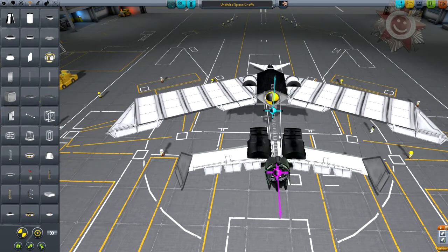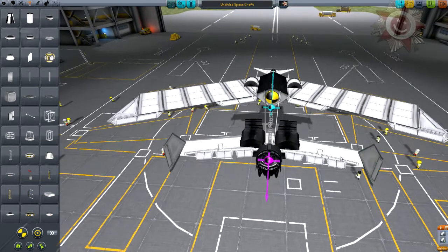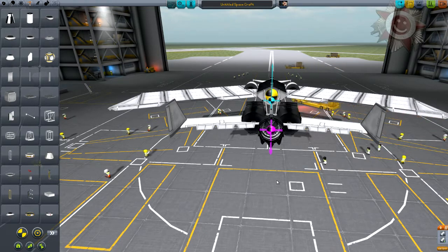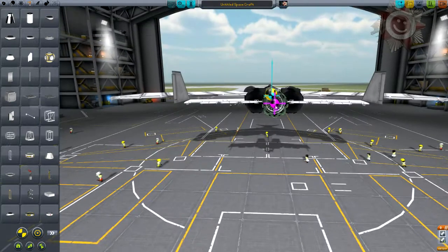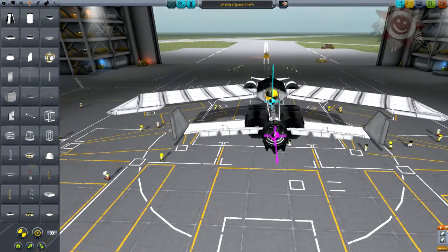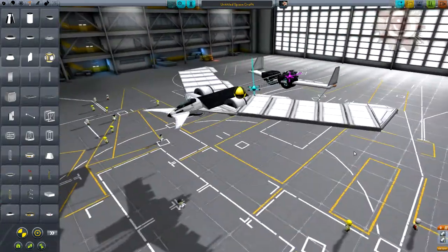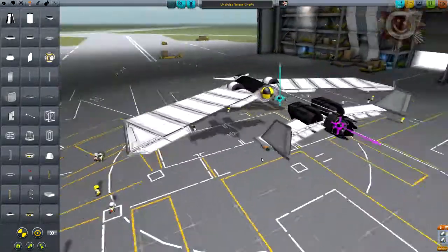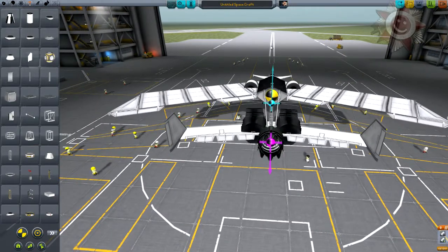The further the engine is from the center line, the more violent the spin will be, or if the engines are running at maximum power, then the spin will be very violent, and maybe you cannot recover from that. But since we have one engine only, and the center of thrust is right here in the middle, we won't have any problems with that. Even if we have an engine flame out at some point, the plane will keep on going straight.